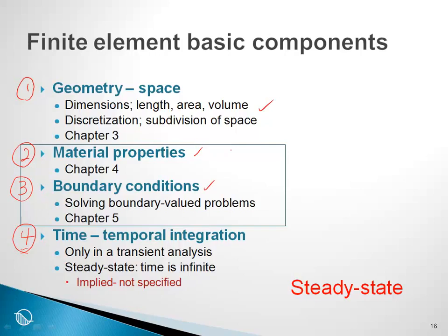So when you do a finite element SEEP/W analysis, you need to spend most of your time not on the geometry, but on the material properties and the boundary conditions. I will come back to this and talk further about this later on in this SEEP/W session.